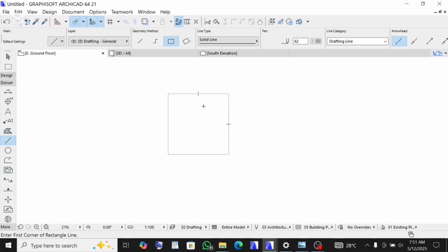Now this is the roof of the building. We are now going to, with the line tool, separate part of the building of this shape using this chained method, like this. For now we are not going to be using this, but for subsequent reasons, that's why I did this here, so that we won't go through the stress of looking for the midpoint when the need arises. So that's why I did this.